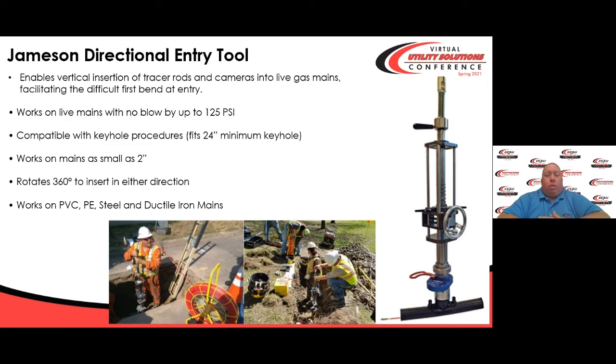The directional entry tool itself will work on PVC, PE, steel, or ductile iron. And the tapping tool and saddles that we've already talked about are obviously for poly only, but there are other fittings on the market that can allow you to get in through PVC, steel, etc.